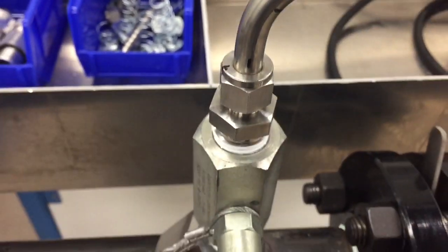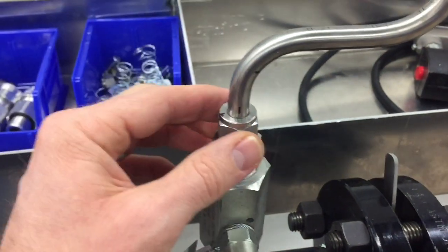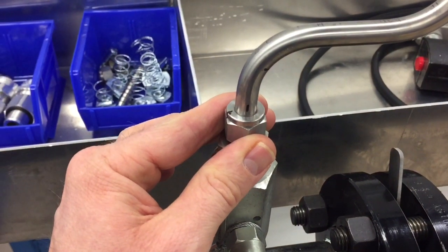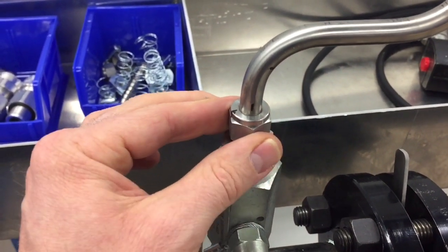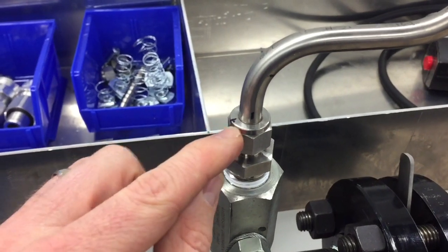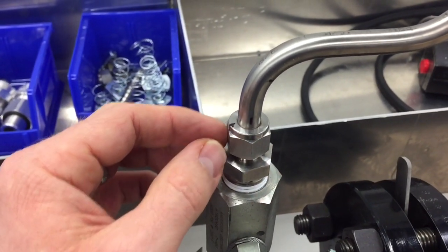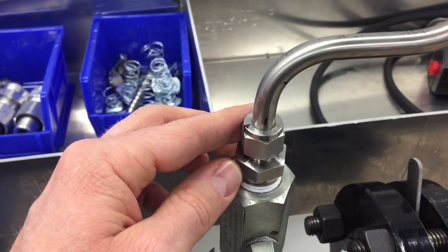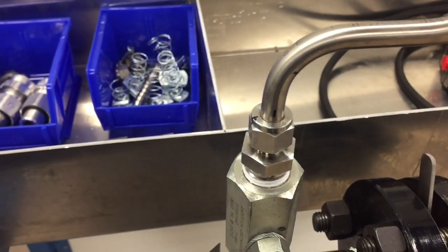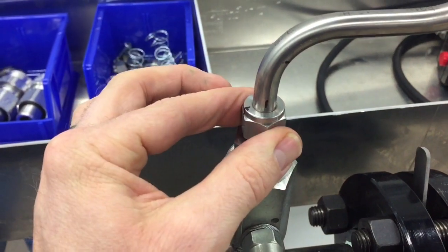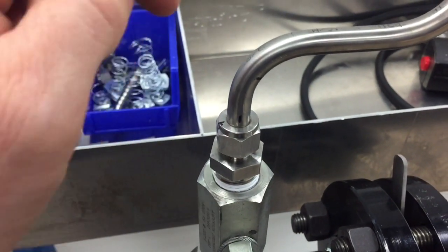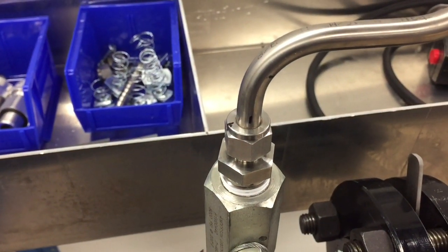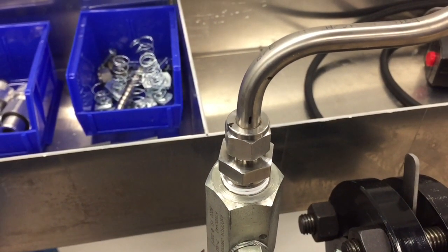The nice thing about these compression fittings is they can easily be removed if we need to service a piece of equipment or anything like that. They're pretty rugged, but it's very important that we have enough of that straight run, and of course that the threads and everything are clean, with no dirt and stuff in there. None of that, because it could cause leaks and things like that. So we want to make sure that they're nice and clean, and that we follow 1 1/4 turns and have enough straight tubing into the fitting so it can compress the ferrule down onto the tube.